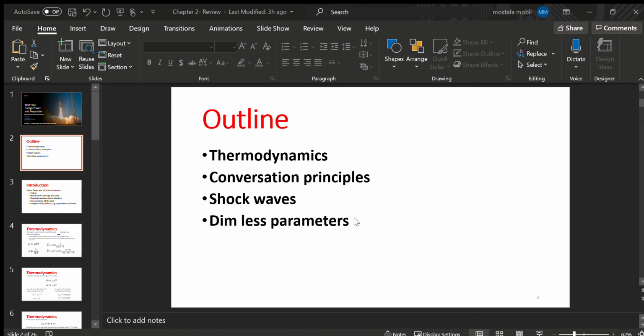And keep in mind that this H_T is not your regular enthalpy, it's total enthalpy. We'll talk about the total conditions in a little bit. If there is no shaft work and your system is adiabatic, your energy must be conserved, right? So the total enthalpy at the exit must be equal to the total enthalpy at the inlet.